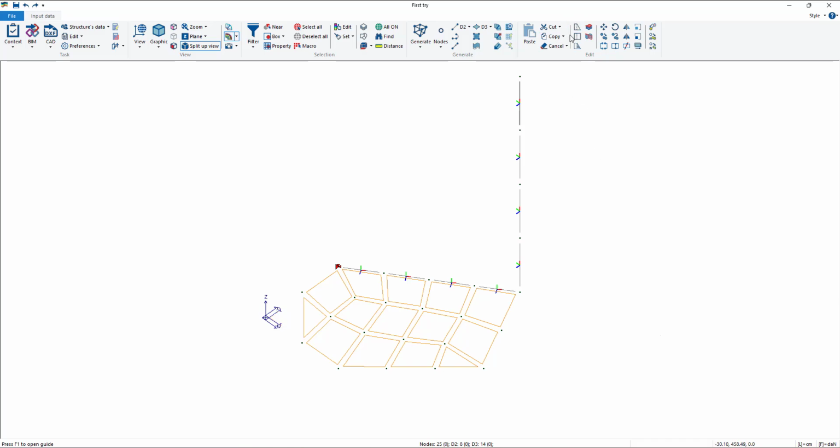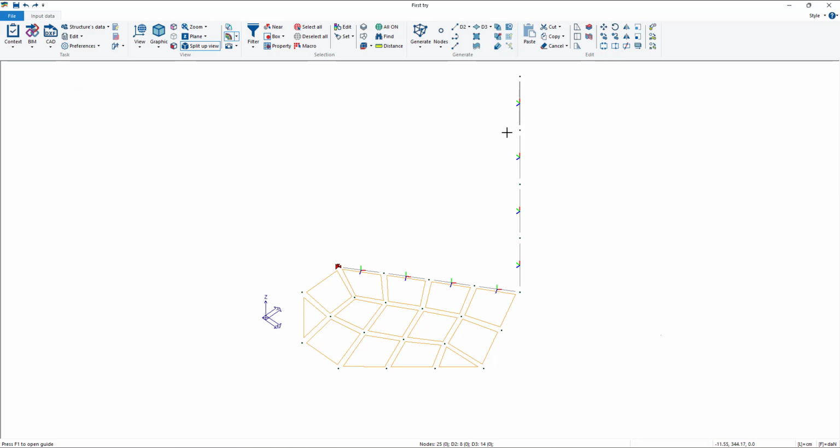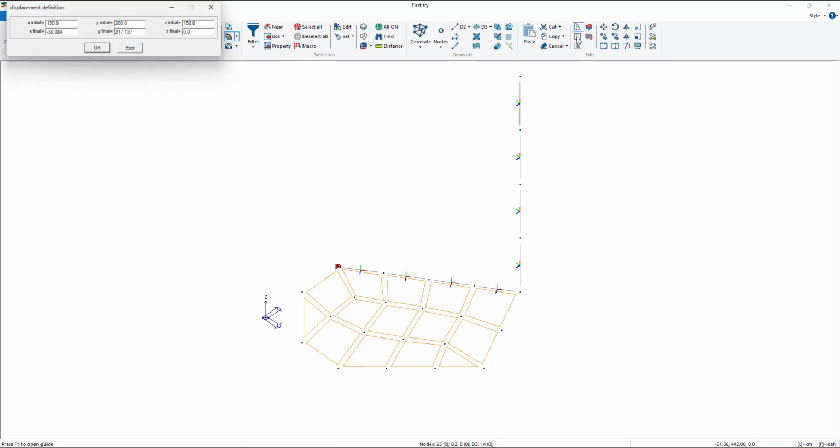Now I use the stretch box, because stretch box moves everything that I select by the exact amount I insert here, and everything else that is connected to these elements moves by consequence. Instead, when I use stretch node, I don't even need to select the node. I just do the first click on a node, and the second one where I want to place it.